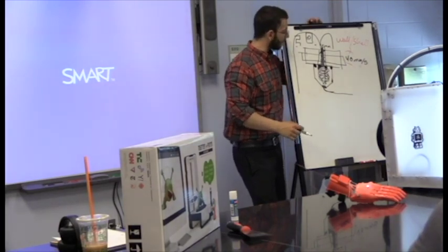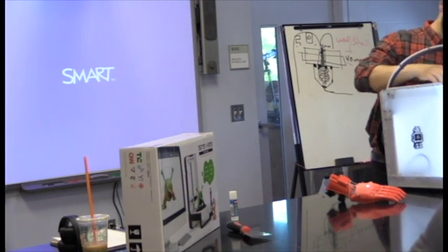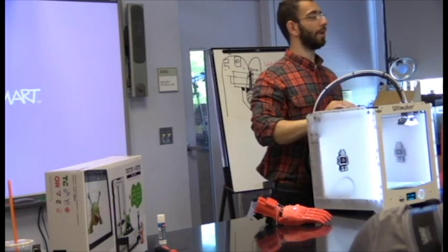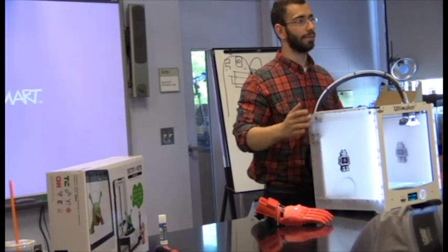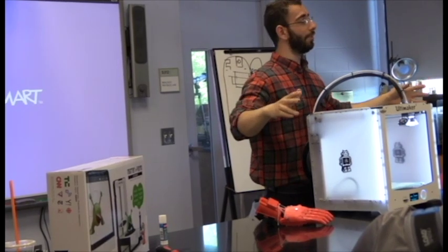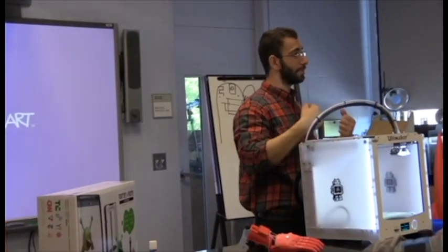And the way to deal with that is you actually have to remove it. I'm going to walk you guys through how to do that. That's the last step before it gets going. Let's just remove it. I'm going to show you how to change filament, and as I do that, I'm going to show you this. Just know that the most common problem, whenever stuff doesn't come out, is because it's clogged. Makes sense, right? Nothing's going through, something's stopping it.